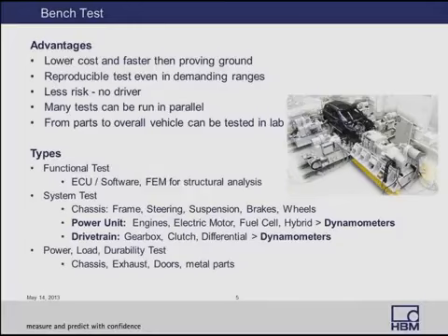These types of tests are further classified into three different types: functional tests, system tests, and durability tests, power load durability tests. In today's discussion, we are going to focus mostly on system tests. And system tests can be further classified as chassis, power unit, and drivetrain tests. For today's discussion on dyno testing, we're going to focus on the powertrain test, drivetrain test, as well as the power unit test, both of which deploy a dynamometer entirely for this application.